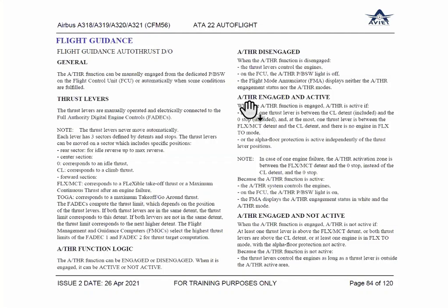This area is clear, right? Auto thrust engaged and active is clear. Now, what is next? Auto thrust engaged but not active. As I said, it is as good as manual thrust. This situation happens when at least one of the levers is above flex MCT, or both levers are above the climb detent. It means you are out of the active thrust range. Then auto thrust will not be there.